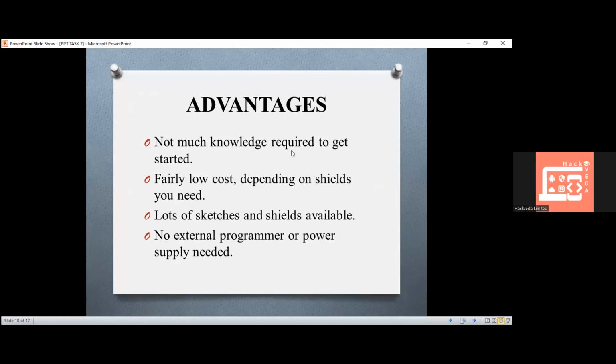Yes, yes. Okay. So what are the advantages of coordinating this Arduino along with all these network protocol devices? There are so many advantages. The very first thing is that not much knowledge is required, because whatever the network we take, it may be Ethernet or Modbus or Wi-Fi, we are making it as we saw in the circuit diagram. We have mentioned only a few connections. For Modbus, there are only three connections: RX to TX, TX to RX, and ground to ground. So we can make a circuit using the configuration of Modbus with Arduino.